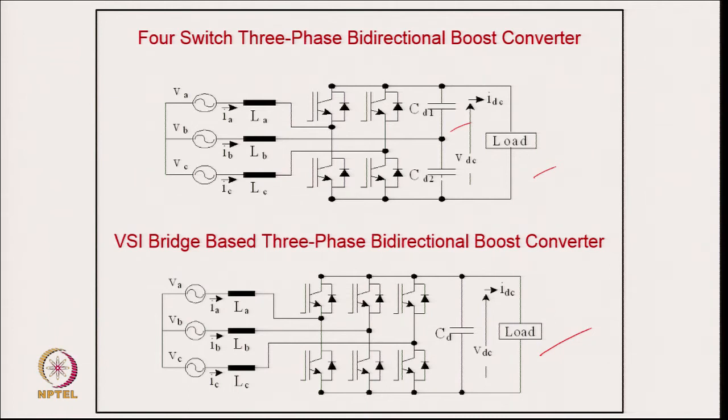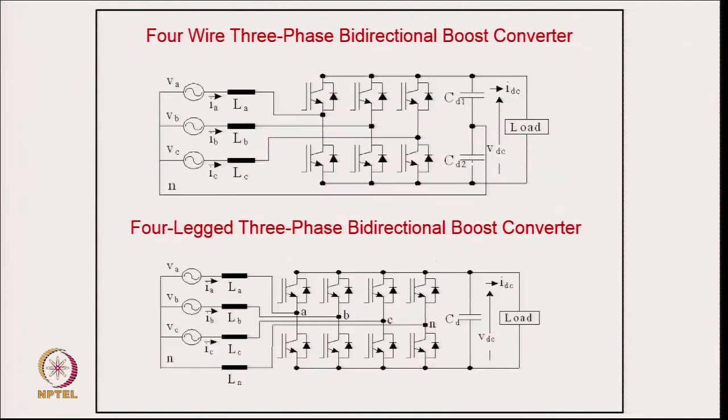So, in the night we do not have solar, you can charge the battery from the grid at unity power factor, and you can put the solar power injection to the grid at unity power factor. Such converters are also now becoming quite popular for renewable energy interface with the energy storage on the DC link itself. So, we would like to discuss that case study separately.